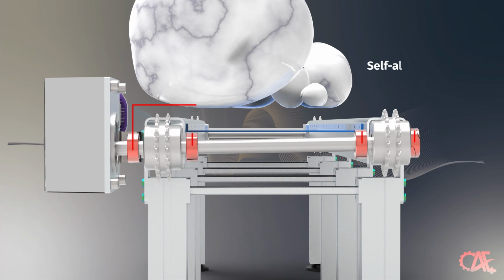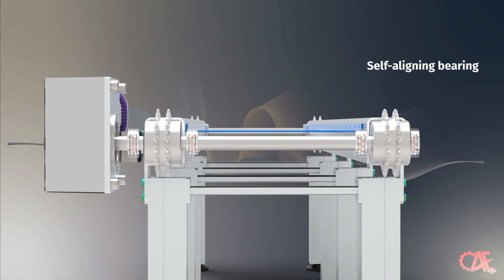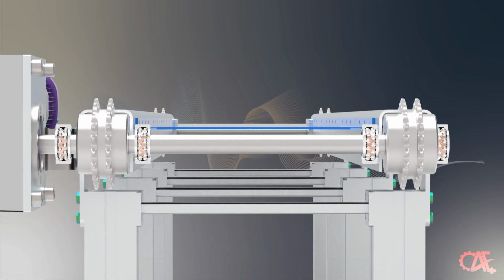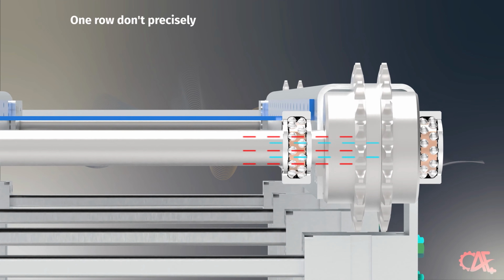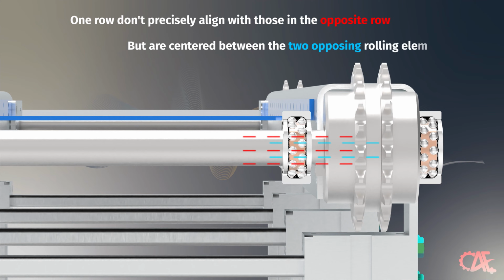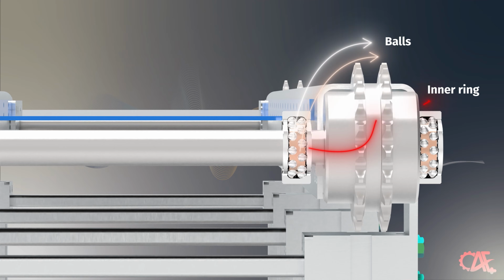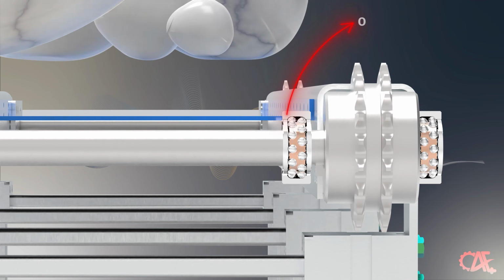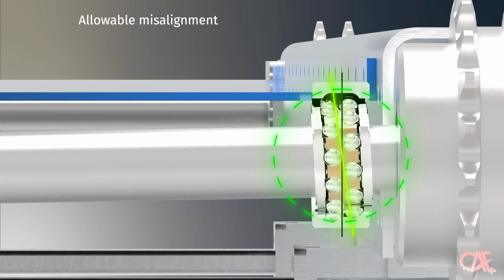We can address this situation by using self-aligning ball bearings. As mentioned earlier, self-aligning ball bearings consist of 2 rows of balls. This design comes with a distinctive feature. The rolling balls in one row don't precisely align with those in the opposite row, but are centered between the 2 opposing rolling elements. This unique arrangement enables the inner ring, balls and cage to pivot or tilt within the outer ring, automatically correcting any misalignment caused by shaft bending or installation error.